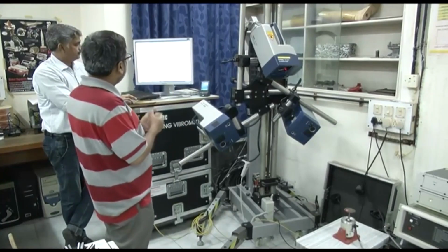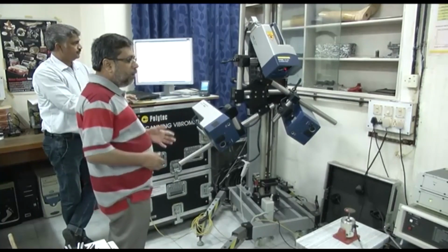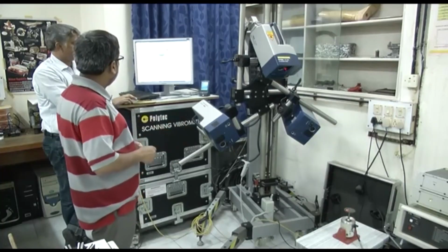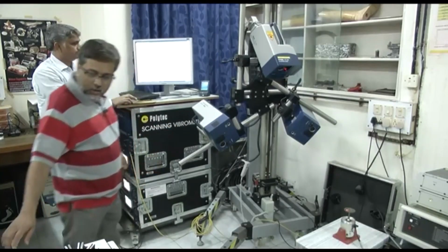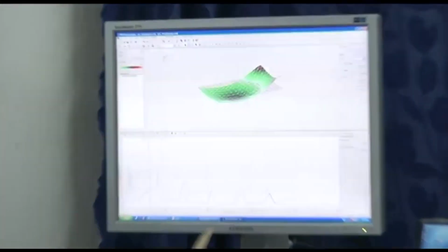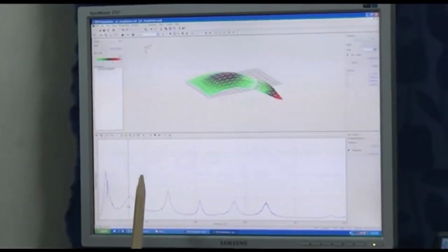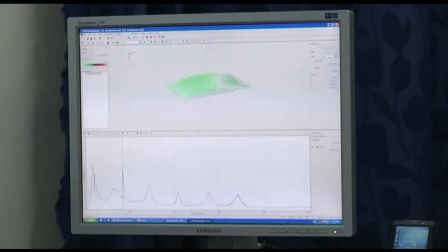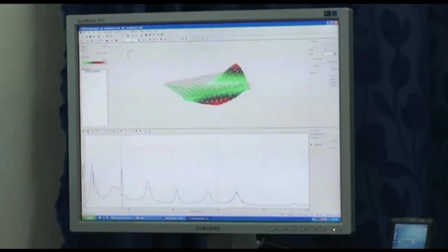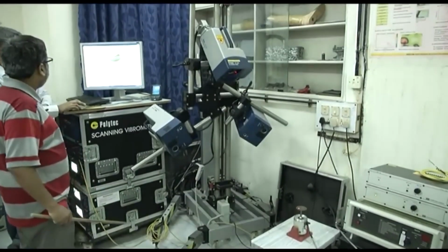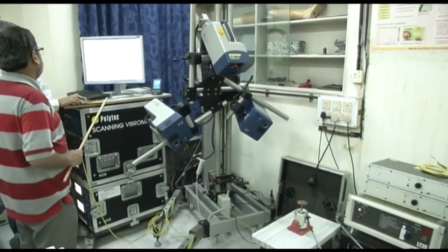If the velocity profile is known to me, then by going through a frequency based decomposition of the signals, I get something here which is also called the FFT of a signal. Can we come to this peak, for example? As you can see, at each such FFT position, it is actually showing the natural frequencies of this particular plate system and how the system is vibrating.